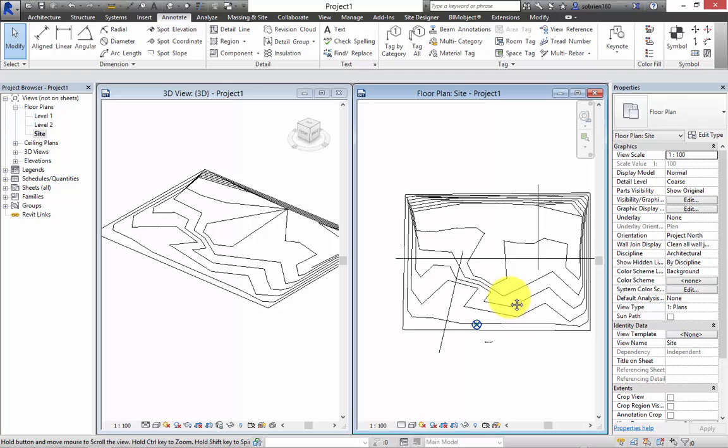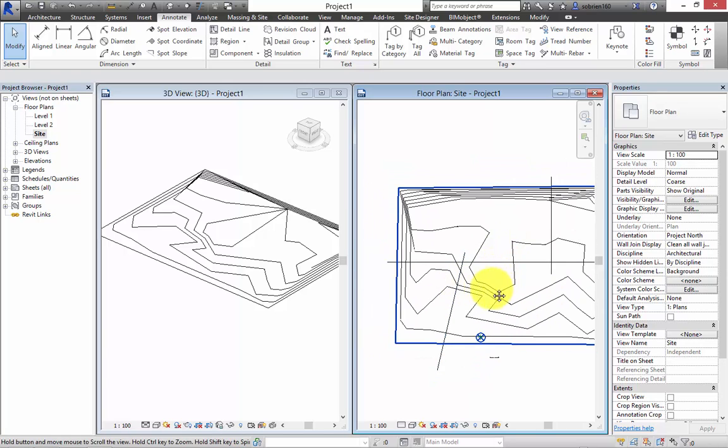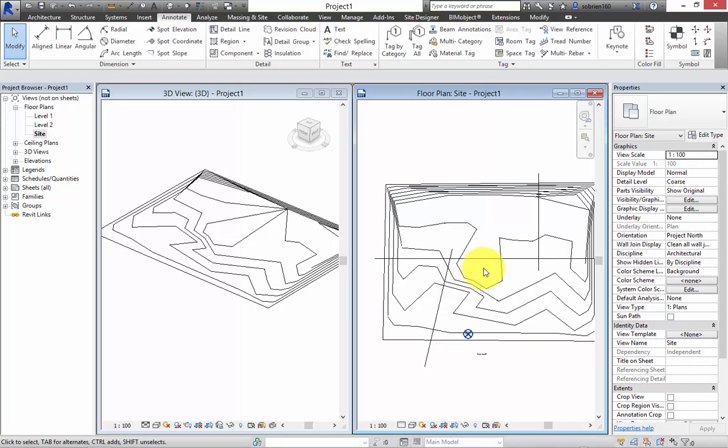Okay? So now we want to add some kind of realism to these lines here. This is where you look at Neufert's, or you look at the local requirements for the area, where they tell you how wide the roads have to be. Usually you have something along the lines of 5.5 to 6 meters for a residential road, and then maybe 10 meters for a main carriageway within a residential estate. So let's just use those figures right now. But it is specific to whatever area you're working in, so you need to use the local standards. Let's say we're going to make this a wide road. We're going to make this 10 meters wide, and we're going to make these two 6 meter wide roads because they're leading into housing areas. So we just want to set it up so it's the right dimensions first of all.